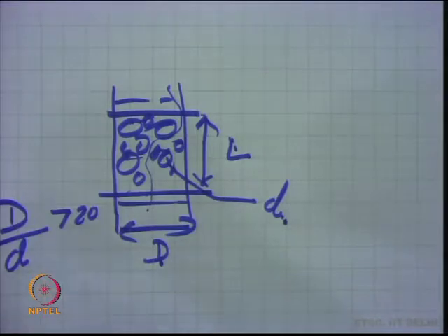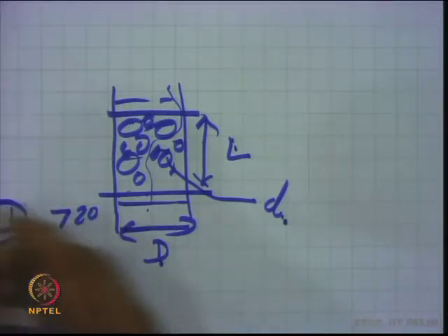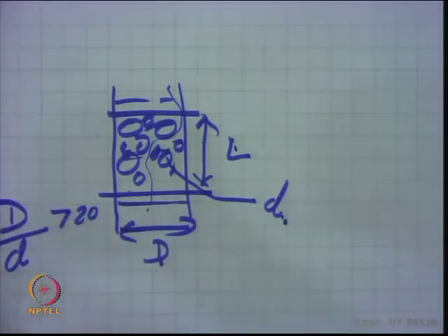Otherwise, when you have a liquid, it has a tendency to move towards the wall, so there will be more wall flow. So, you need to decide these factors depending upon the hydrodynamic study, and these are very important when you look at the actual reactor design or when you model the reactor. We need to introduce those non-ideal parameters in terms of the axial dispersion and radial dispersion.